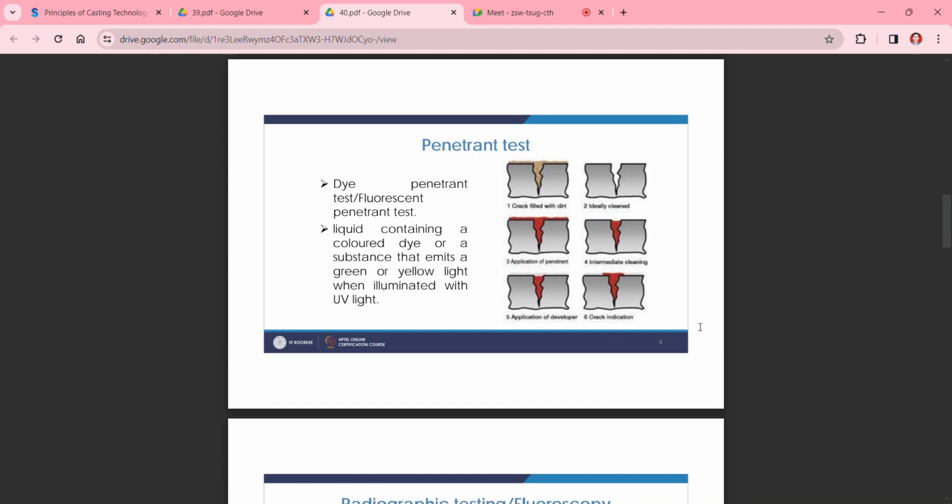If we talk about a surface casting defect, that will go down into your sample up to some extent. That level can be micrometers or it can be millimeters. So you can grind that surface. If it is only up to some micrometers, then you can grind that surface and you can use your castings.